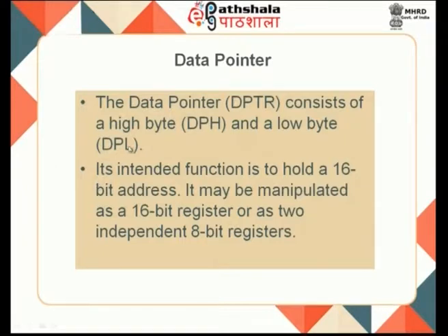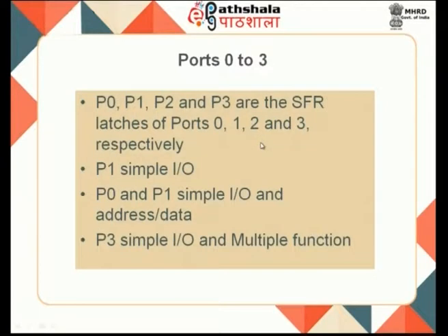When I am using these together, I can store a 16-bit address. It always holds an address that refers to the external memory. Its intended function is to hold a 16-bit address. It may be manipulated as a 16-bit register or two independent 8-bit registers used as a pointer to external memory.